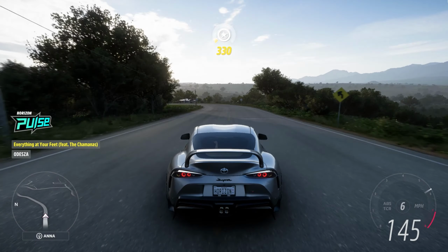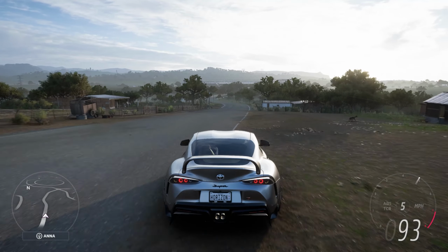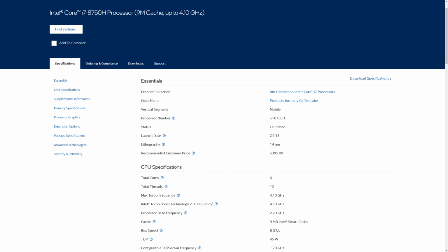A bit of theory. You should always start by looking through the official CPU specification. In reality, the topic is much more complex, but without going into detail, there are three main CPU characteristics that we are interested in. Thermal design power, or TDP, represents the average power in watts the processor dissipates when operating at base frequency with all cores active under an Intel-defined high-complexity workload.